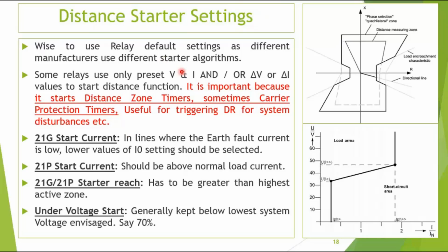Okay. But this is not a part of the tripping mechanism. Understand this. Now it is wise to use relay default setting, as different manufacturers use different starter algorithms. So better not use our own brains on it. Certain basic guidelines can be followed.